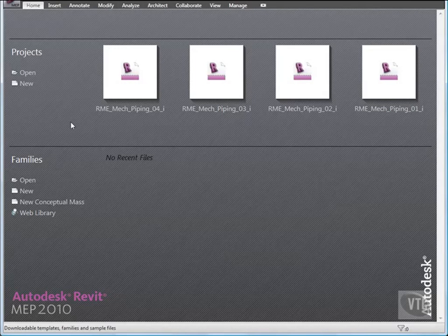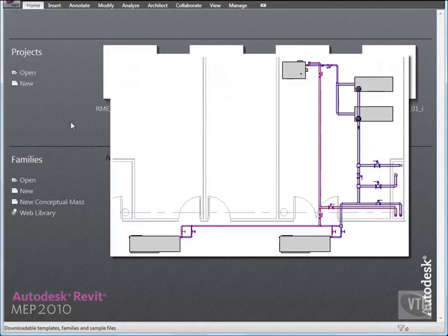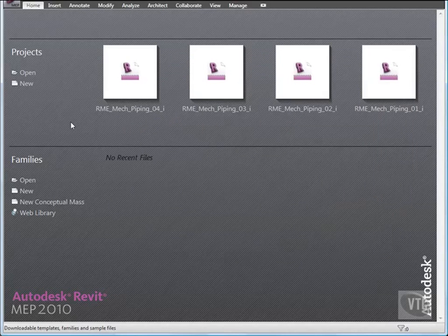In this lesson, you will add valves to model the piping for 2 modes, cooling mode and heating mode. You will add a bypass valve to stop the flow and direct it to the cooling tower in the cooling mode. When the valve is open, the water bypasses the cooling tower and is heated by the boiler. You will also add shutoff valves to control the flow to and from the cooling tower.